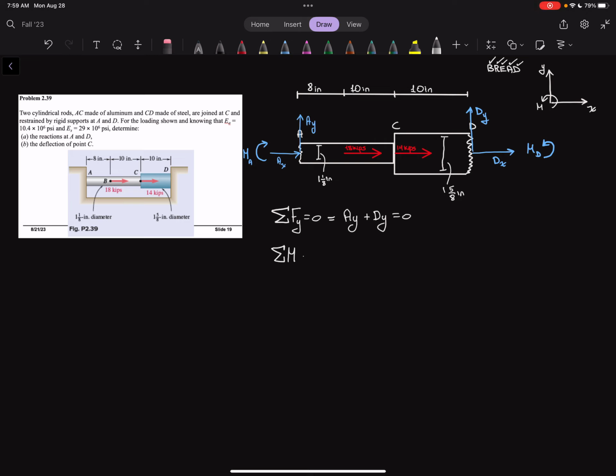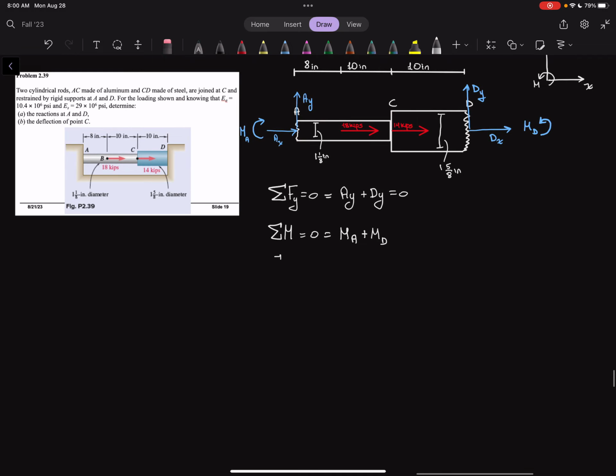Well, we have two moments, and those are free moments, moment A and a moment at D. And again, these are reaction moments, so they react to some other forces applying a moment. However, if we don't consider the vertical reaction forces, the horizontal ones pass through these points, and so those cannot create a moment, and the red ones do as well. So we also know that we don't have any moments. So that's good. Now let's look at the sum of the forces in the x direction.